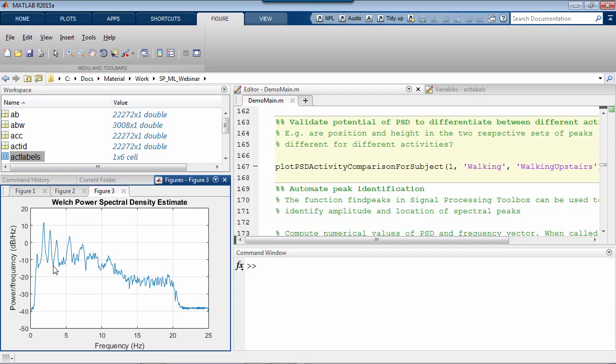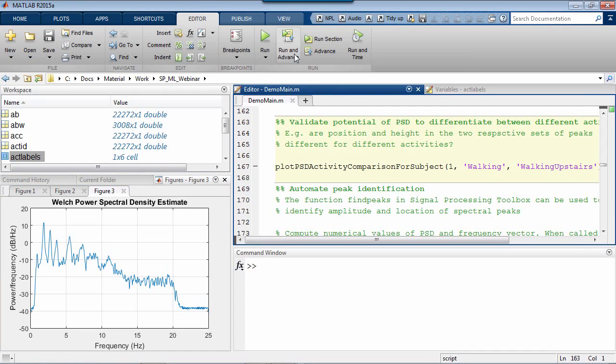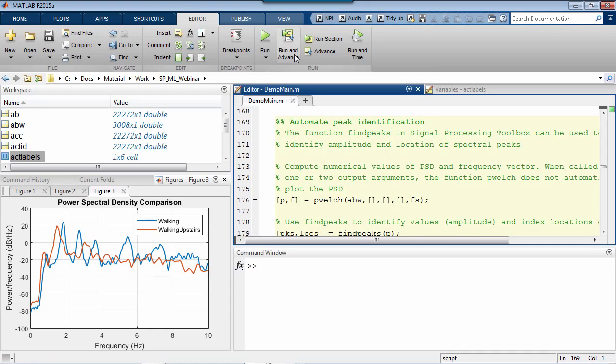For our signals, this pattern of peaks between 0 and 10 Hz with higher energy holds a lot of measurable information. If you ever sat in a signal theory class, you remember the spectra of signals that are periodic or almost periodic. We can see a fundamental frequency, roughly around 1 Hz, and a number of harmonics at positions multiple of that frequency. As for extracting information from this, the distance in frequency between these peaks is the rate of time domain oscillations, and the relative amplitudes of the peaks describe the shape of oscillations, a bit like the timbre in musical signals.